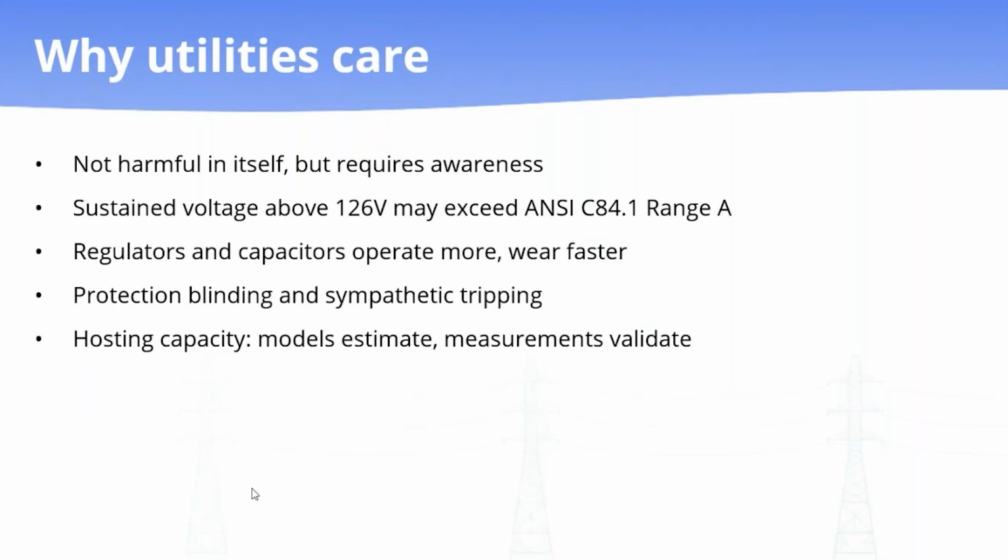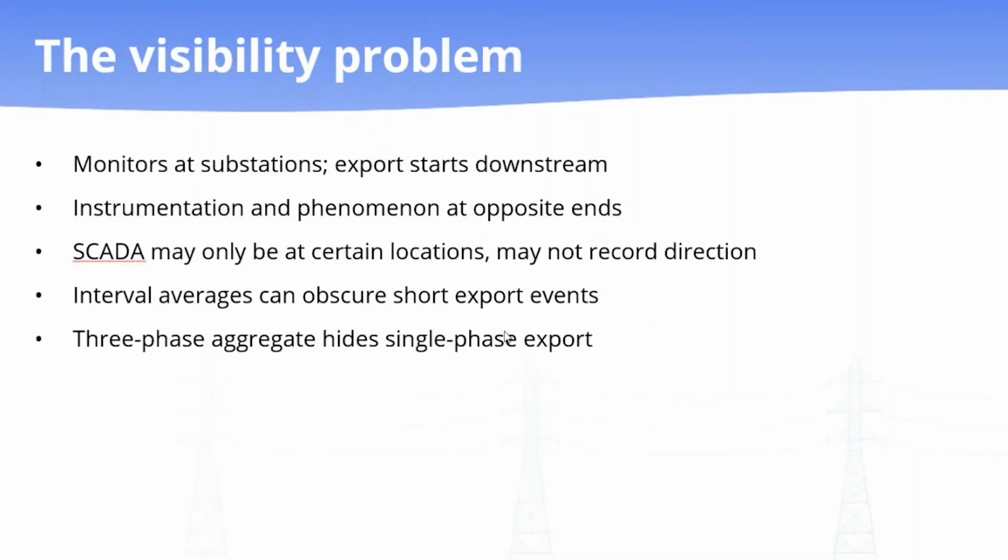Export raises conductor loading, changes transformer loading profiles, and shifts regulation requirements. Hosting capacity studies estimate all that, but they're models. Measurements tell you whether those conditions actually occur, how often, and how severely. Reverse flow is hard to see for a structural reason.